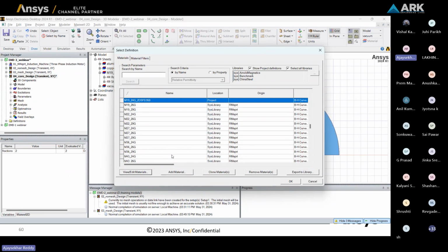So these real-time scenarios change the core loss value which we have calculated through the simulation. When a design engineer is working on a real-time part, after considering all these, we can expect a minimum of 30 percent change in the core loss when comparing with the simulation. This is quite normal, but still we can make it possible to reduce the error here. So let's see.